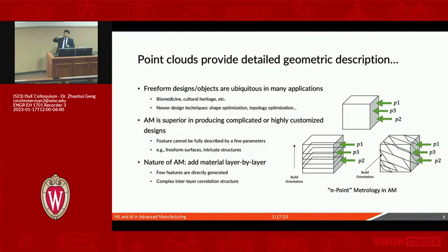But in additive manufacturing, we are producing this part in a layer-by-layer fashion. So if we are still utilizing 3-point or even endpoint measurements on this side surface, they only give us some information about the different layers rather than the whole feature, right? In a more extreme case, if we change the build orientation to an arbitrary orientation, none of the surfaces are directly fabricated. If we still utilize 3-point measurements, they only give us partial geometric information of those layers and of the features, which is not very useful for controlling or monitoring additive manufacturing processes, right?